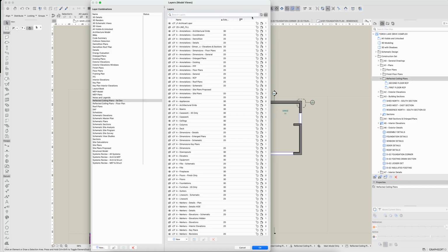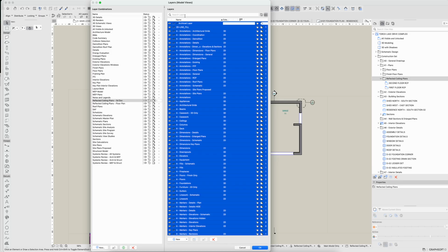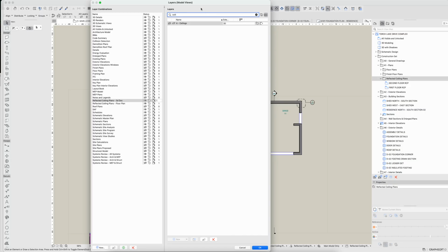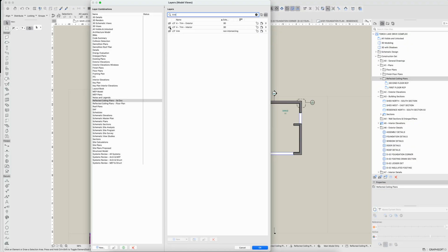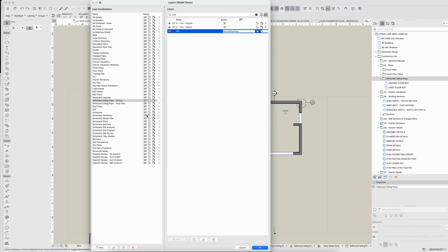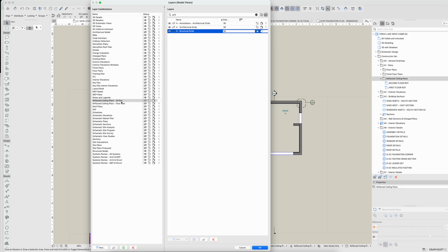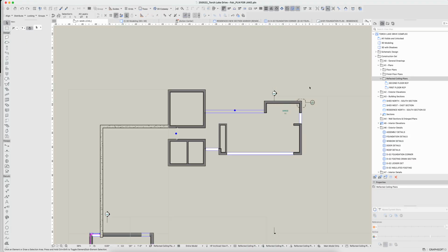And then this layer combination here, I'm going to turn off all layers for the 3D doc, and I'm going to put only the ceilings, beams, trim. We'll put interior and exterior and non-intersecting trim on here. Basically everything from the cut plane up. We can also put our grids on this one as well, and that's going to allow us to line these up on the layout.